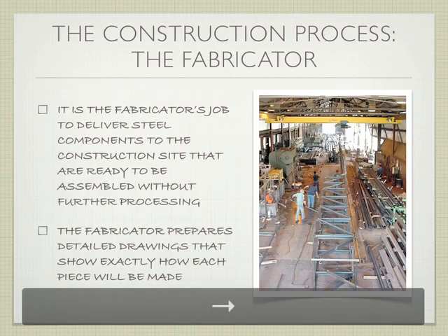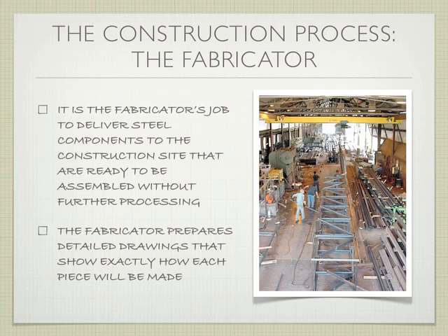What you're going to do is send this job to a fabricator. It's a separate independent entity, and their job, basically, is to deliver the steel components to the sites so that they can be built. They're going to make up whatever the connections are going to be. They're going to make up the correct lengths of the pieces and that sort of thing. That's their job. But in order for them to do that, they have to first decide how all of it should actually be made. How many bolts should bolt these two pieces together? What kind of welds should be used? That sort of thing.